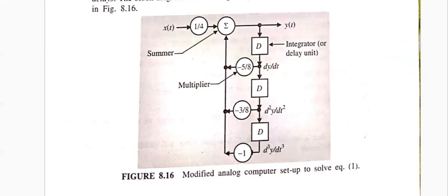In the discrete domain, you can control this integrator part. We do not need to design it with a circuit like the operational amplifier, but we can use the flip-flop to control this delay value as well. Probably you can understand how to introduce the delay.